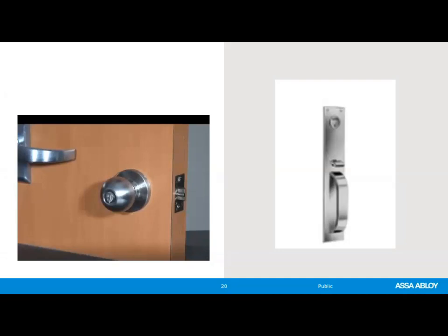Question came up: a clear opening with swing clear hinges would still be measured between the face of the stops. I believe you said we would get the full width of the door. Not the full width of the door, because you still have a 5/8 stop on one side and a 5/8 stop on the other. What I said was you're going to be able to pick up that 1 3/4, whatever the thickness of the door. Yes, you're measuring from the face of the door to the face of the stop when the door is open 90 degrees, but now the face of that door is right in line with the face of the stop. So whatever is between doorstop to doorstop would be your clear open width. Good question.